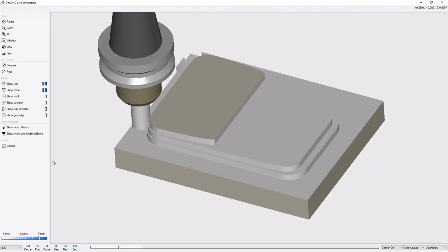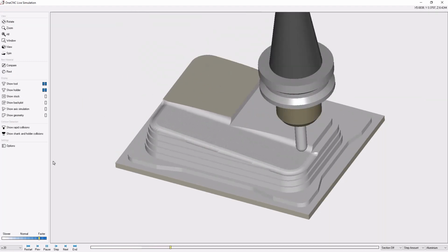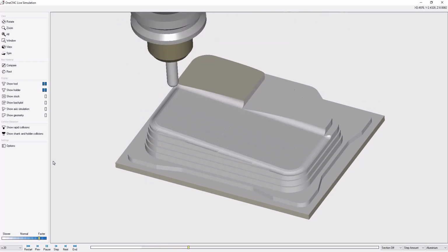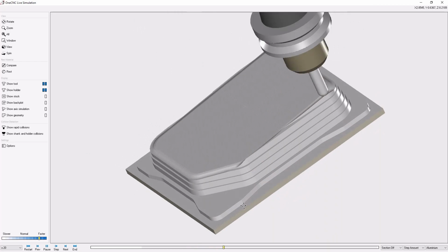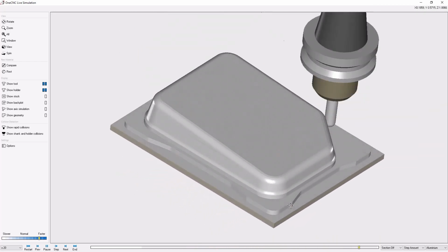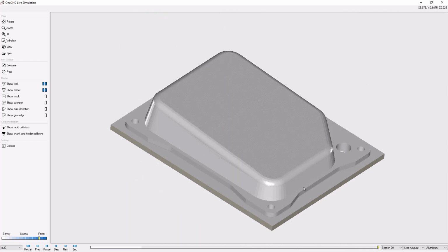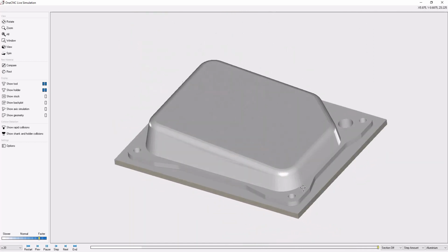So to begin with, we have our roughing operation. Then we have our planar finish facing operation to machine the top of the part. And then we're using a Z-level finish command to finish the outside of the part. Now because it's a ball-end mill, we came back in with a taper tool to make that sharp edge and then drill the holes. All right, that's it for this training video.